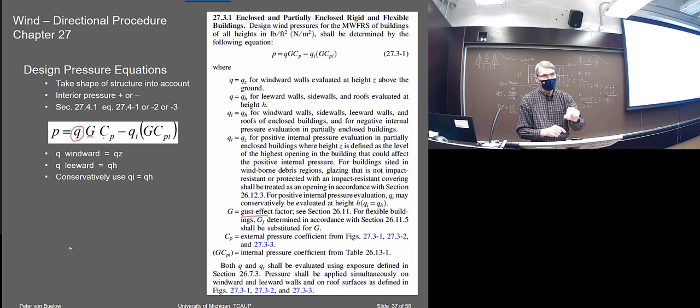This is the factor CP for that point on the building, and then depending on what velocity you want to take for the wind, you just multiply that pressure times the CP, and you get the pressure on the building, right? Okay, and this is exterior, and this is interior.